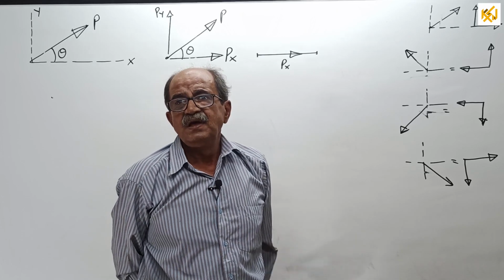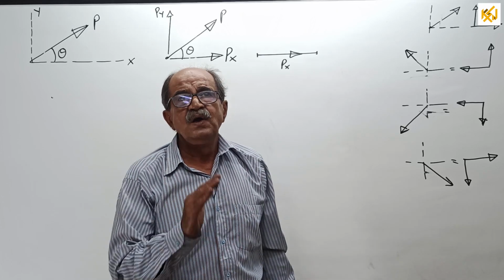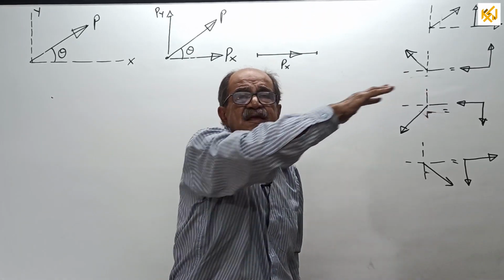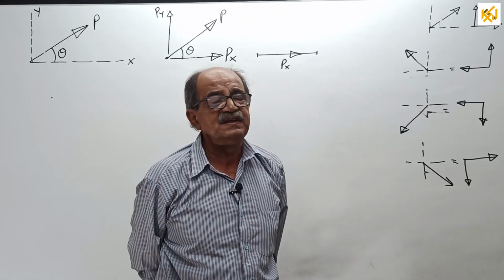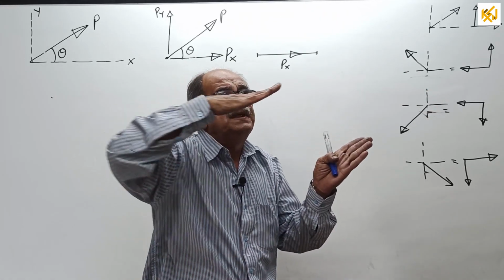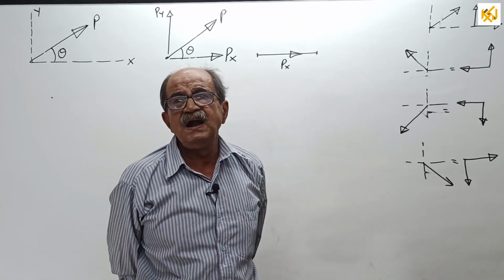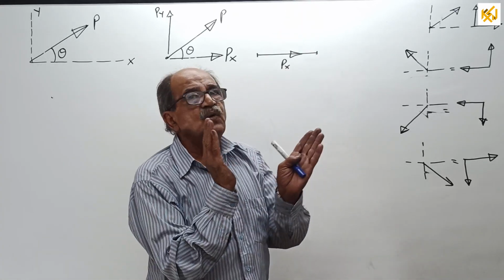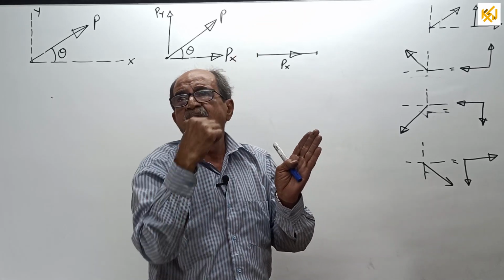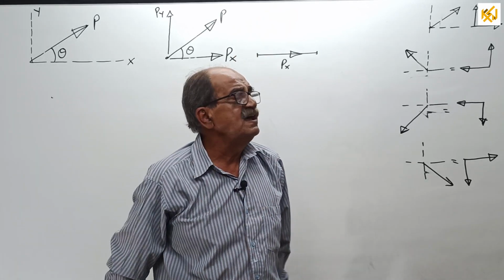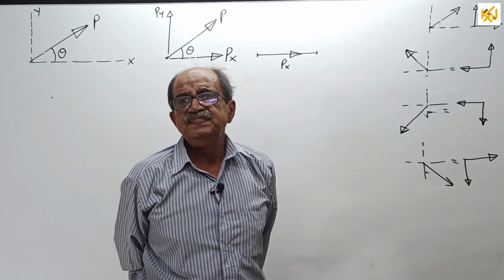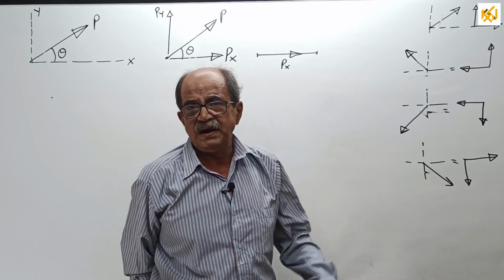At that time, you might have heard of the formula. For a parabola of this type, the area is 2/3 base into height. Whereas for a parabola of this type, the area is 1/3 base into height. Whereas for a parabola of this type, from one end up to the center, the center of gravity will be at 3/8 and 5/8 of that base.